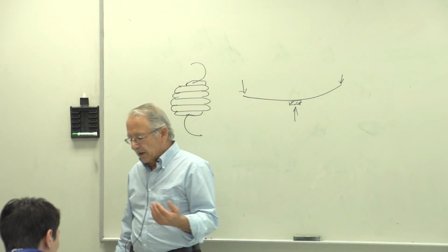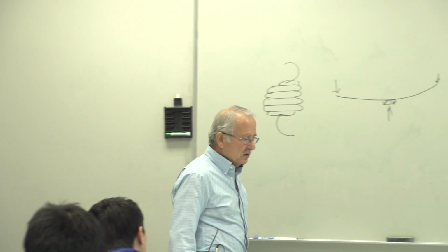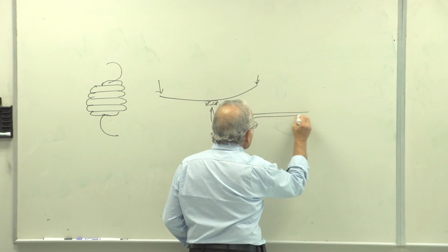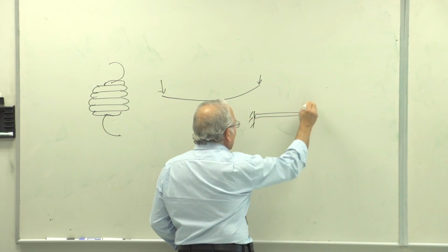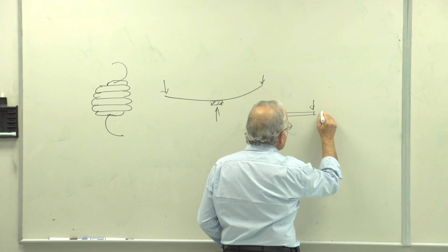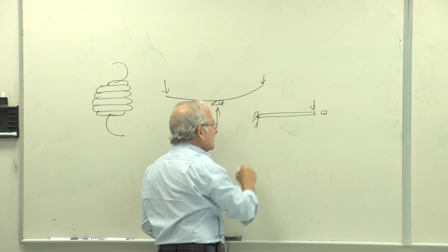We can have flat springs. We can have constant force springs, constant stress springs, so that the spring looks like a cantilever, essentially. If you look at it from the side, it looks like this. And generally, if you have a cross-sectional area here that looks like that, well, then your stresses are maximum over here.